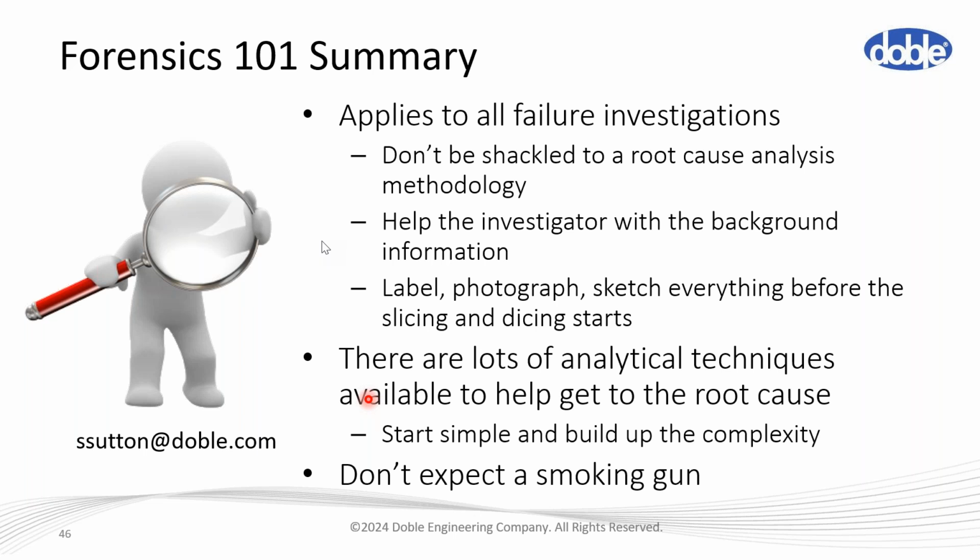If it's not going to fail through water treeing, usually in polymeric cables, periodic PD testing is probably the best approach, along with routine maintenance to make sure things like the earthing systems are fine. You don't have excessive circulating currents. You don't have sheath damage, etc. So it's your periodic maintenance, maybe supplemented with something like partial discharge.